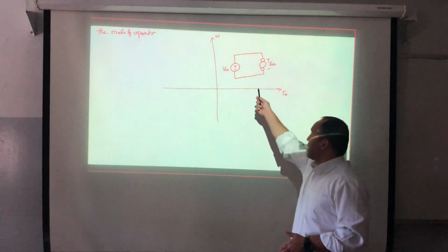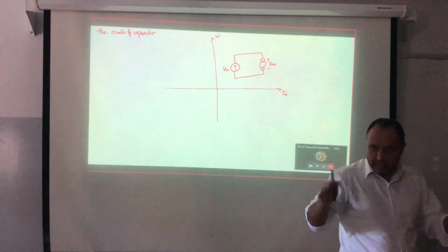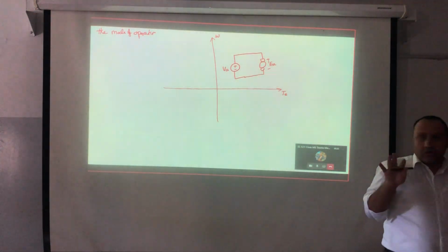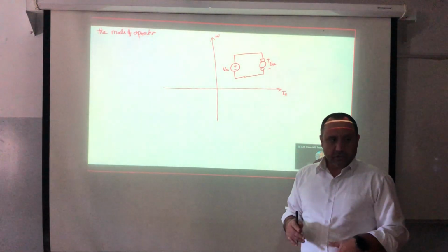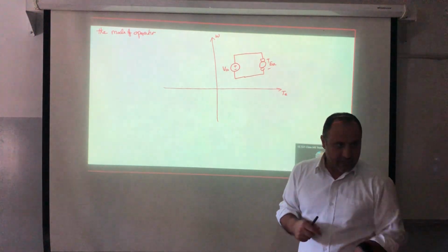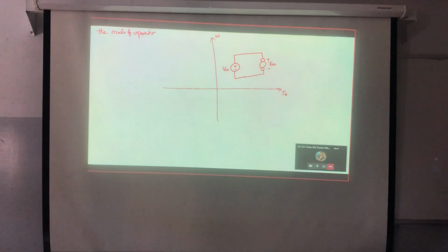Of course, here we have a resistance in between, which is the RA, but simply, I will assume it's inside the machine. So for the machine to draw a current, VA must be greater than EA. So here in the first case, VA is greater than EA, and both are positive.